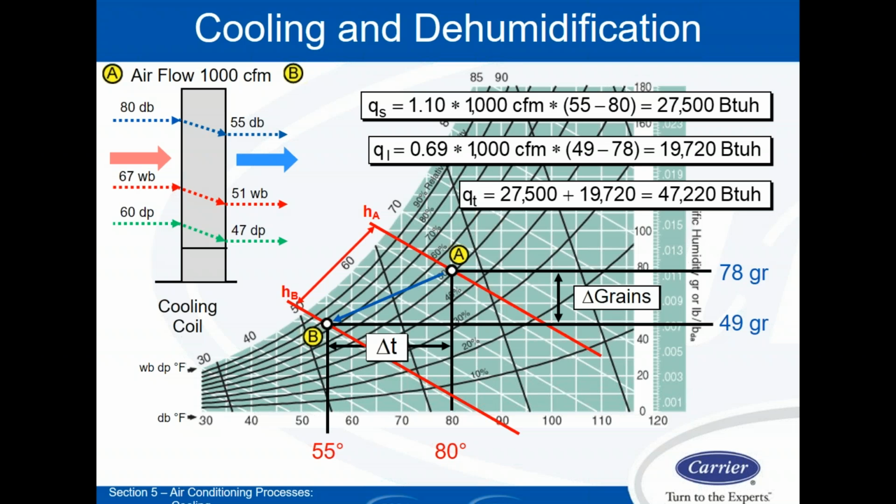So Henry was asking for clarification on our poll question regarding cooling. He said that he believes that it is D on a high temperature, high humidity day, meaning that it moves left and down. But on a low humidity day, he thinks it's B, it moves to the right. So it can't be to the right because moving to the right means I'm adding heat. So you're saying that when I run my cooling system, I'm going to actually make the temperature warmer.